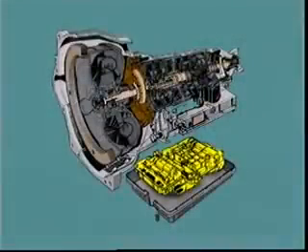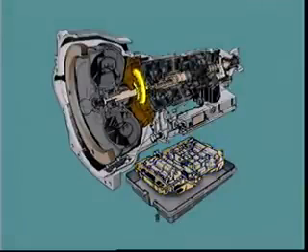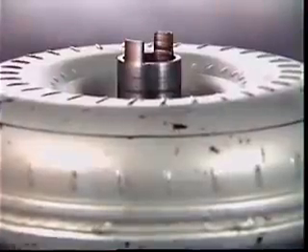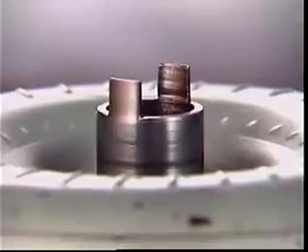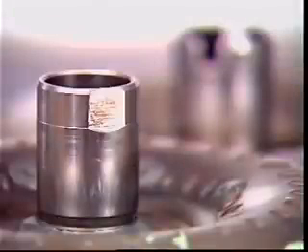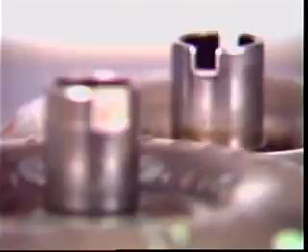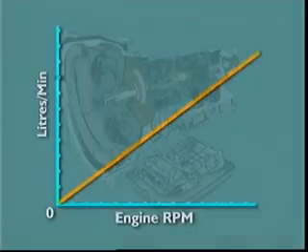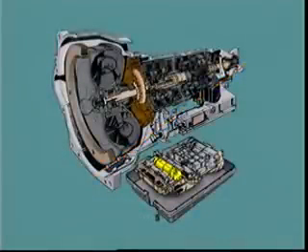The hydraulic control system requires a continuous supply of fluid under pressure, normally provided by a fixed displacement pump. It is driven by the torque converter when the engine is running. The pump driving member is engaged by tangs on the converter spout, or machined flats, or by slots. Pump output always exceeds normal operating demands, so pressures are controlled by regulating valves.